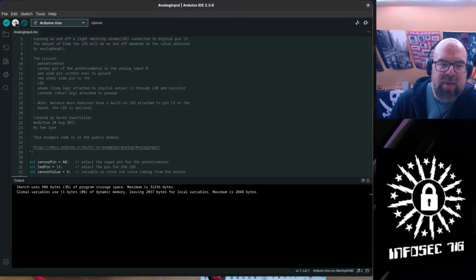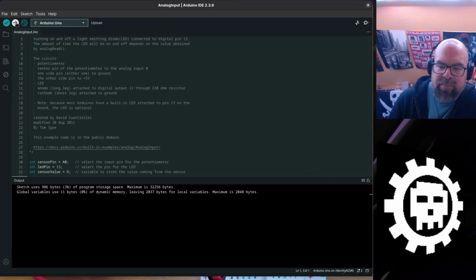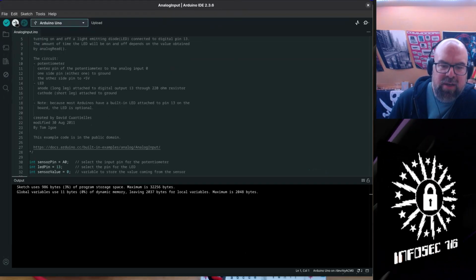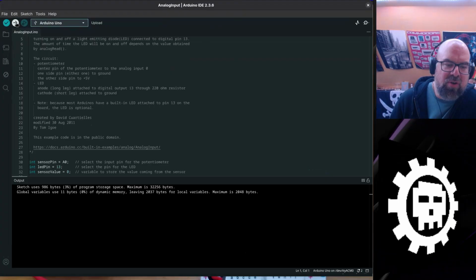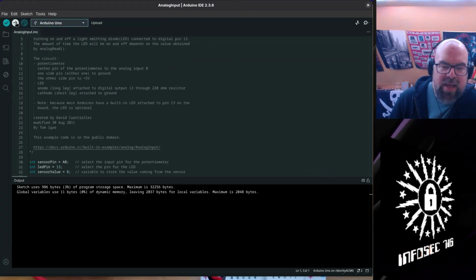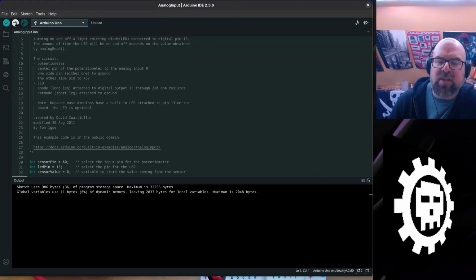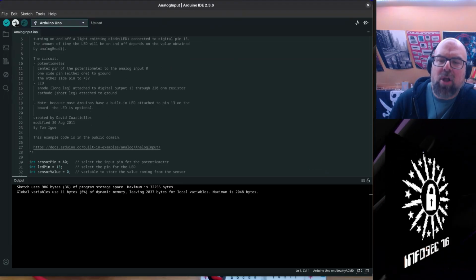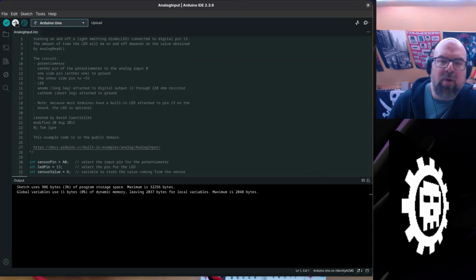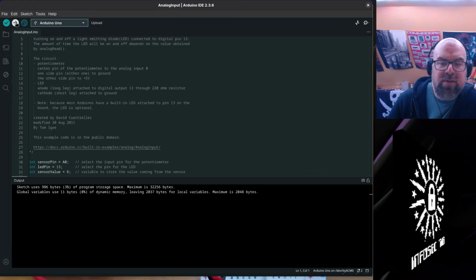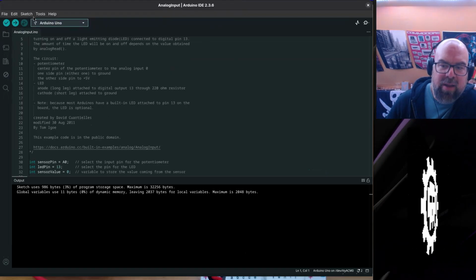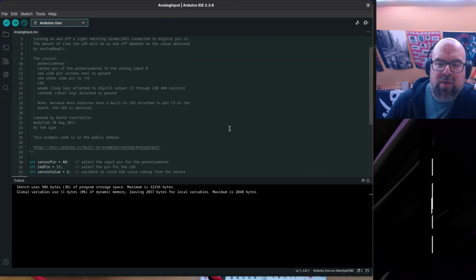If we wanted something that activates a circuit when soil humidity reaches a certain level, we can do that with a humidity sensor, right? There are a lot of these analog inputs that we can use with the Arduino. And now we know how to do it. You just hook it up to one of the analog input pins, account for it programmatically in the Arduino, and then write your program to generate the outputs that you want.